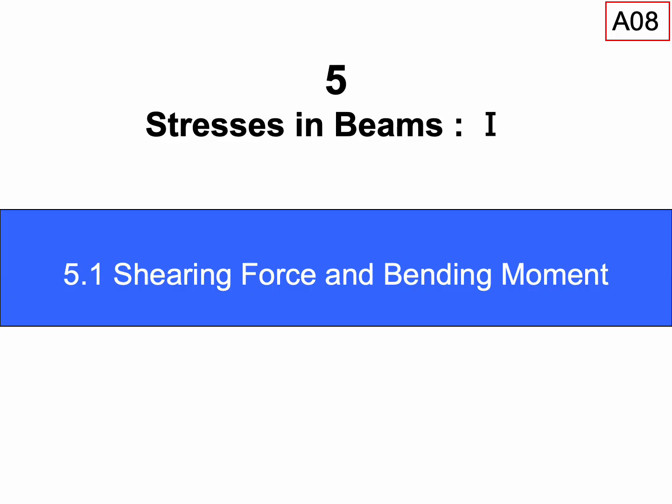We identify two foundational types, the simple beam and the cantilever beam. A simple beam is characterized by supports at its ends, which allow it to span a distance. In contrast, a cantilever beam is fixed rigidly at one end, leaving the other end free.